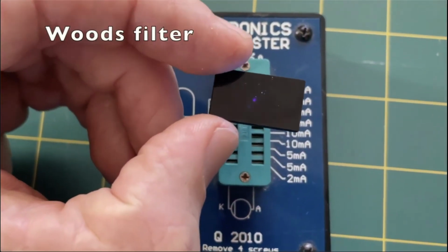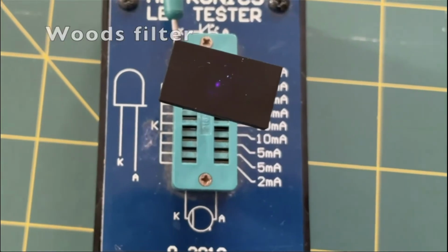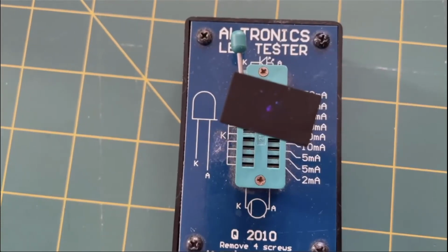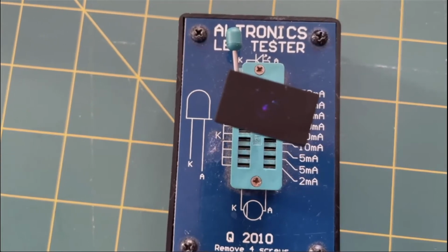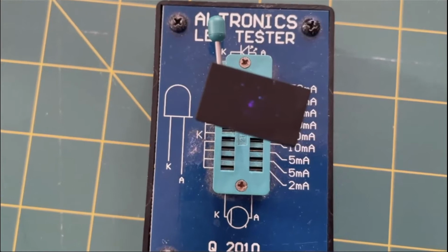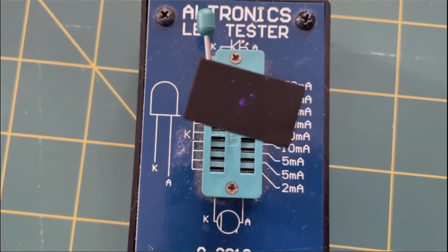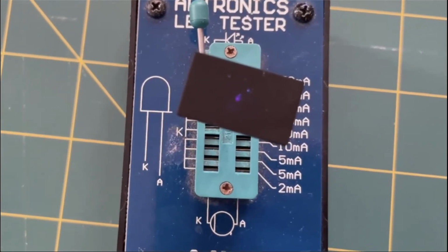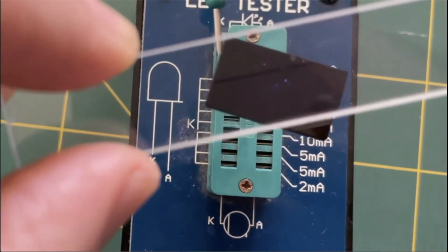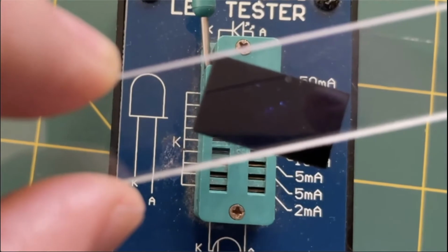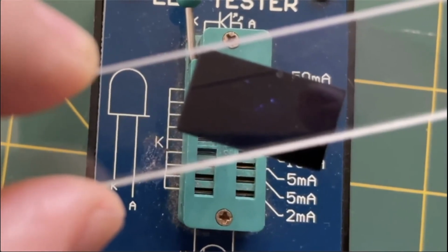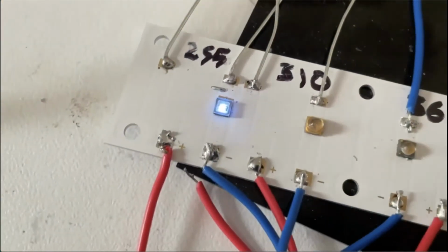Here we have what is known as a Woods filter, blocking out the visible. Ah, I hear you say, but I can still see it. Well, actually, I can't, and nor would you if you're in my seat. You see, the phone camera can detect the UV and tends to show it as purple. So from an instrument perspective, a second filter is needed to prevent any UV reaching the camera, as this is often used to view and record fluorescence.